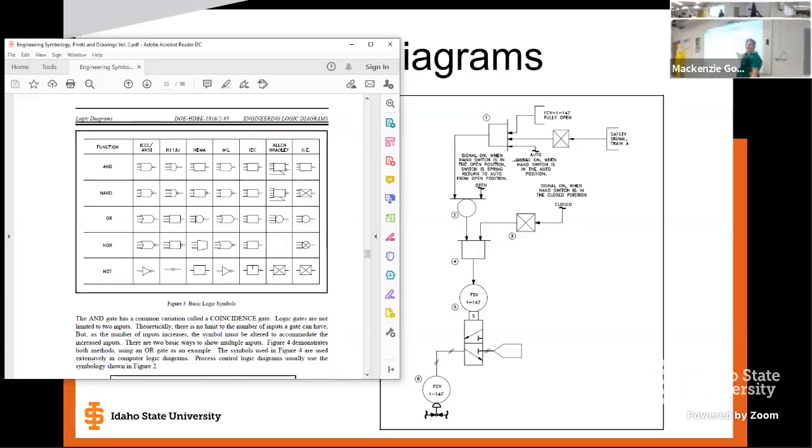Okay. And that drawing that your finger's on is conforming to the nuclear standard. Now, what I say that, you might occasionally find a place where their drafter used to work for an IEEE place, and their drawings at that nuclear power plant are a little different. So understand, when you go to work someplace and you start looking at their drawings, ask for their symbology. Okay? But in general, at the 3 plants that I've worked at, so every one at INL, I'll just count that as one, and then the 2 NRC reactors I've been at, this is what I've seen consistently at all of those.